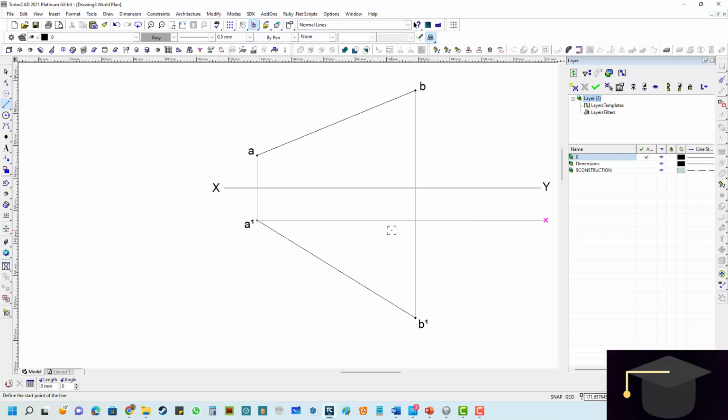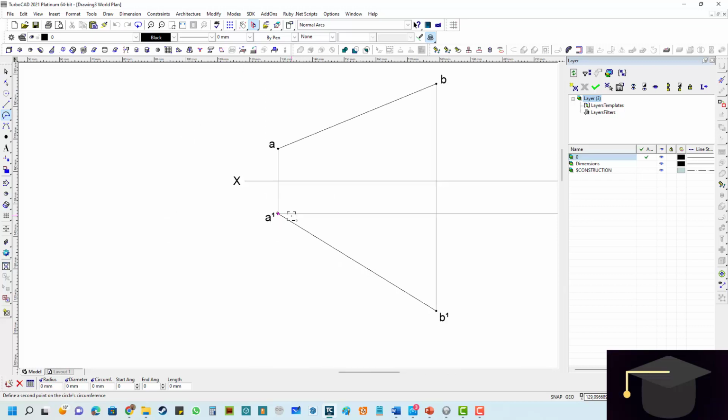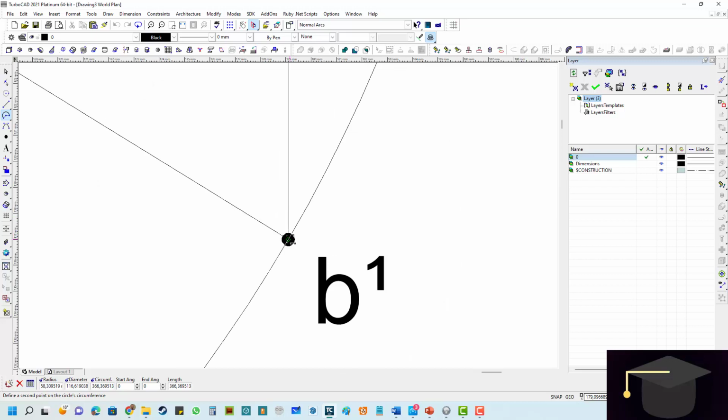That's the first step. The next step, what I do on paper, you will take your compass. On CAD, I'm just going to take my arc tool. So I'm going to click and hold on the circle here on the far left, and then I will find the arc and center radius tool over here. Select it. Zoom in onto that center point. Press I to make sure I've got the center intersection. Move my mouse all the way to the intersection of B, and make sure it's right there.